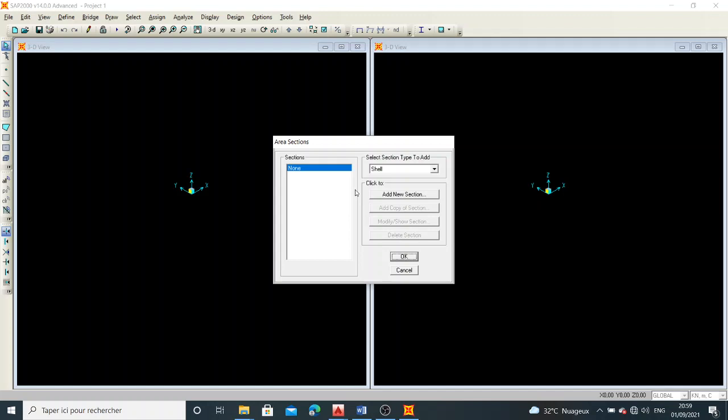The software will recognize the slab as a slab, but it will not have any weight, meaning that we will add all the charges or all the weights, the dead loads of the slab onto the slab manually, and then the live loads as well. But then if we just put it as a concrete slab, it means that it will account for its dead load, and then we'll only be adding for what? The live loads.